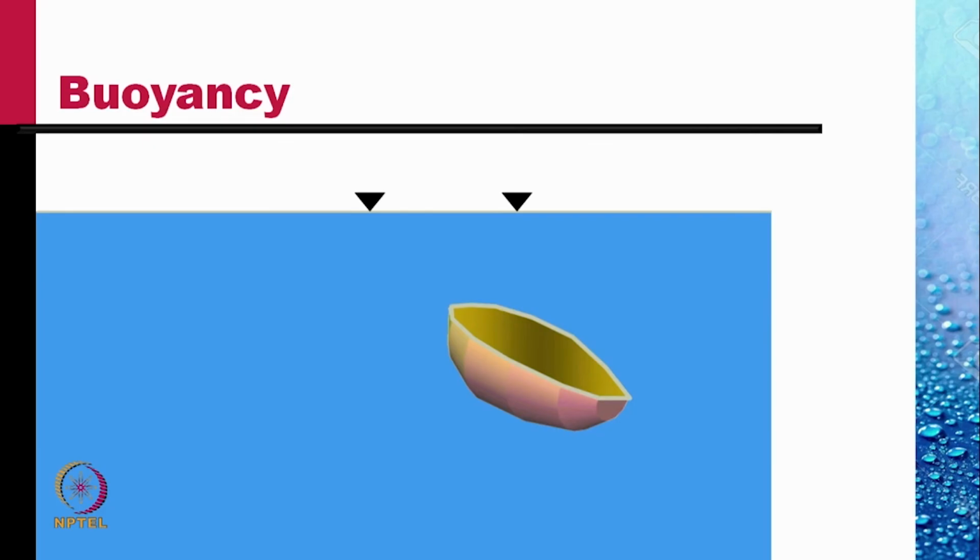The vertical force acting on the bottom half, which will act upward at the bottom, is equal to the weight of the liquid supported by this, so the weight of the darker blue column of water up to the lower half surface. This is of course acting downwards on the water, and so it is acting upwards on the surface shown.